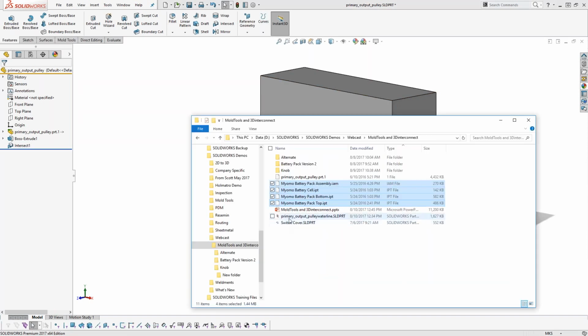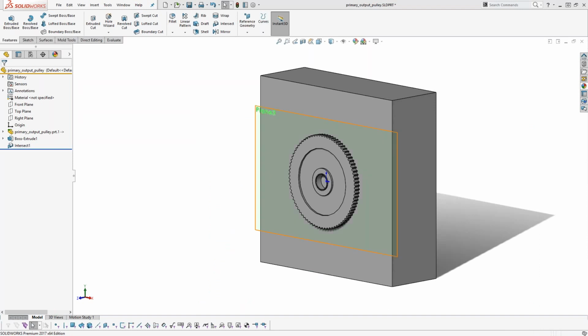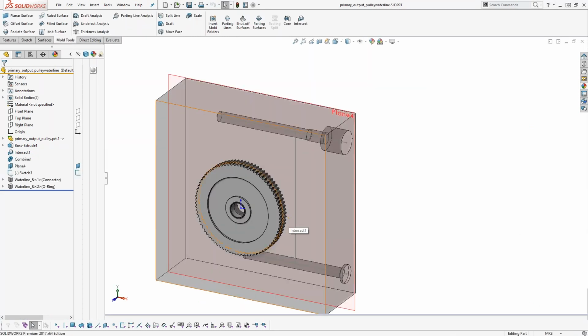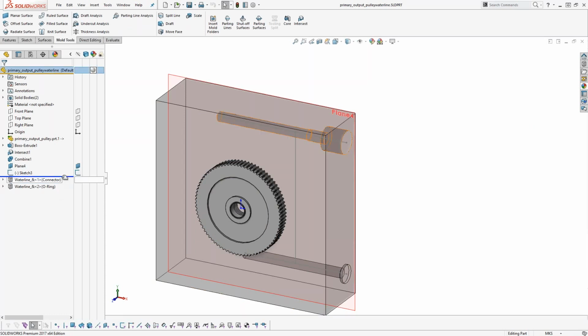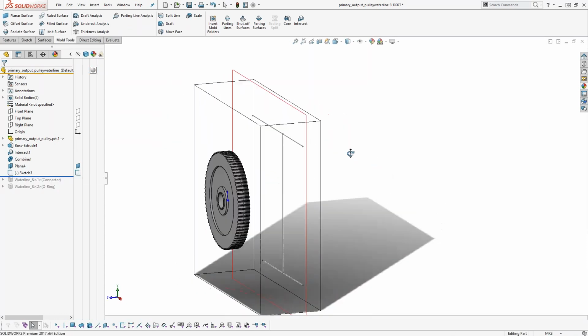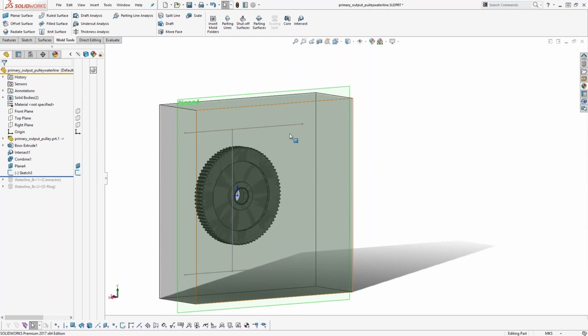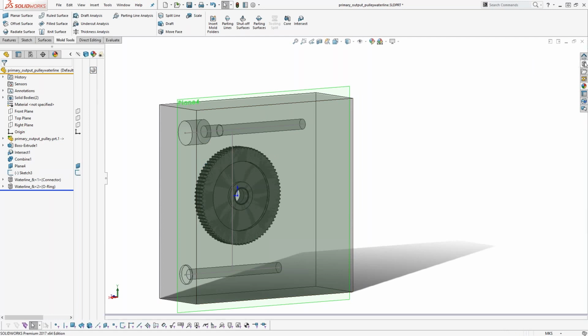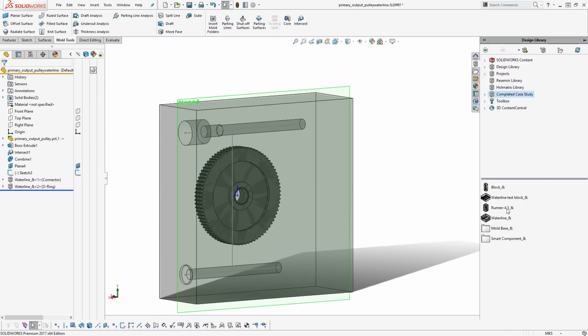So what I'm going to do is just open up this waterline model. So we look at this model, I've got some water lines put in. These are library features. So these are maybe their company standards, and the way they're put in, we can put them in just by sketching out some lines for where we want them to go and then dropping them in. You can see I have one more left here, so I'm actually just going to go in and drop that in. We can go into the library.